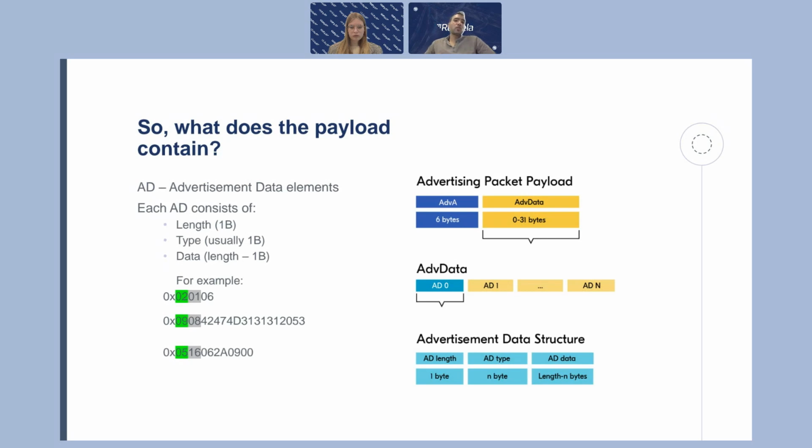And the last part, the data field, contains the actual sensor information. Different manufacturers structure this information differently. This is exactly why custom BLE support is very powerful, because it allows you as a user to define how the tracker should interpret this data structure. Once the packet structure is understood, integration becomes much easier, faster, and more flexible at the same time.